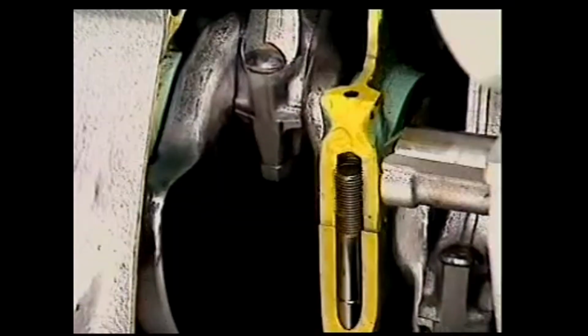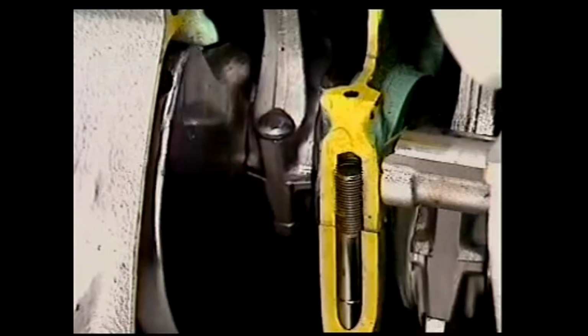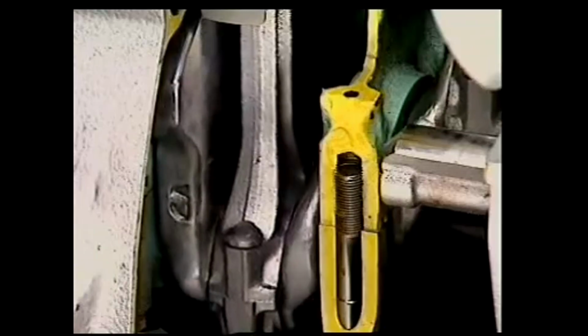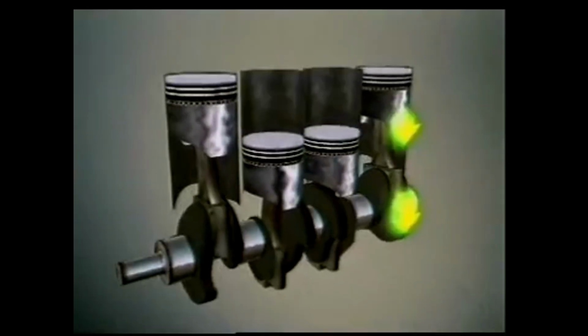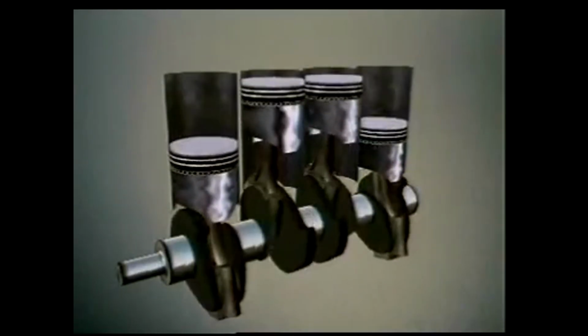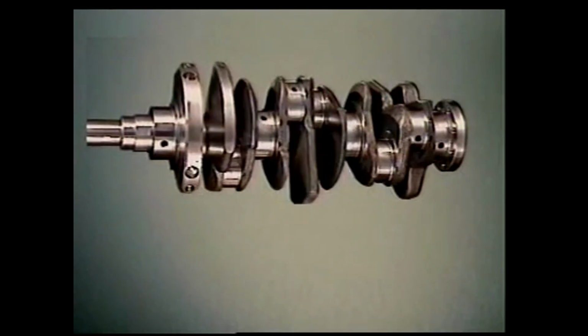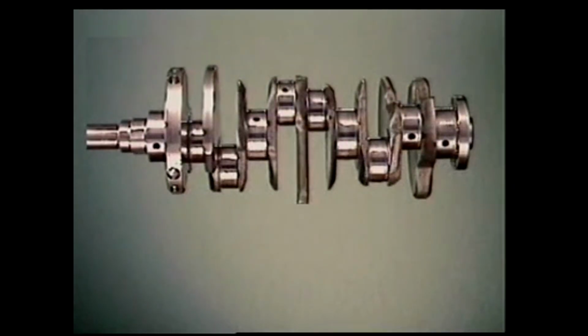The crankshaft turns because of the forces transmitted through the connecting rods. At the same time, it must be held in place. That's done by bearings. They reduce friction and allow free movement. The crankshaft is held in place in the engine block by main bearings at points called journals. Different bearings do different jobs. These bearings support the crankshaft in place, but let it turn freely.